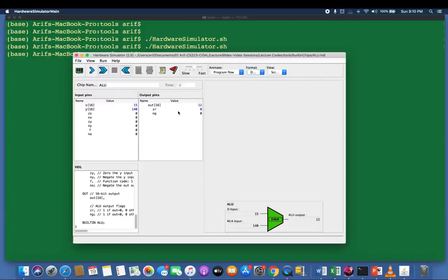You can always see the 6 control bits for performing the not Y operation are 110001. So I need to change these control bits: 110 and then 001. Once again, don't need to memorize them. So the control bits given to the ALU now are for the operation not Y, and Y is 140. Let me change it to binary.